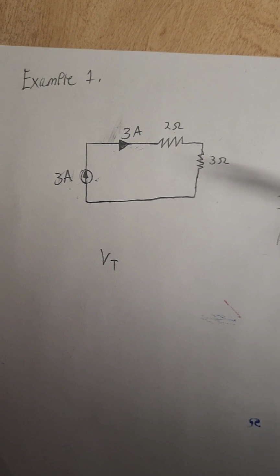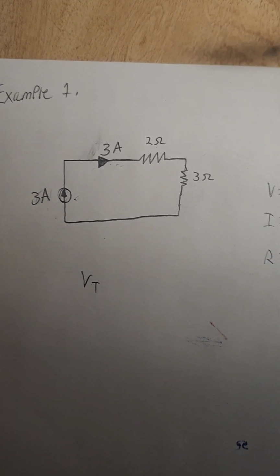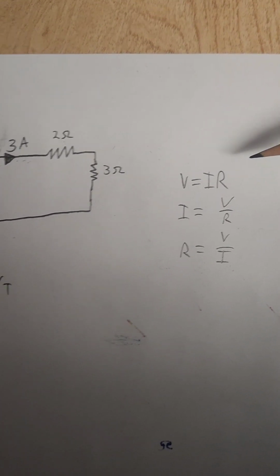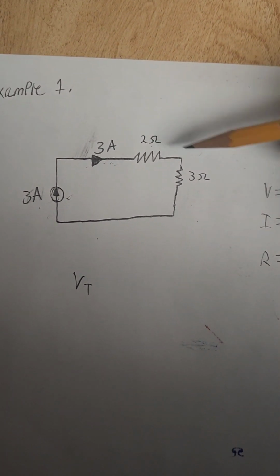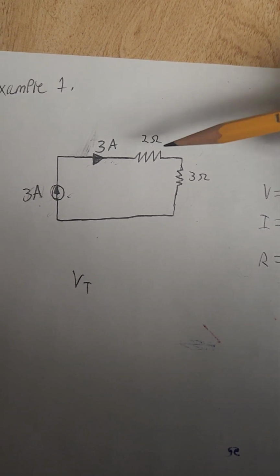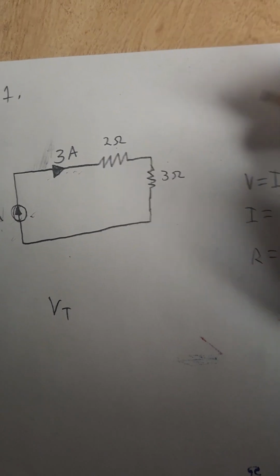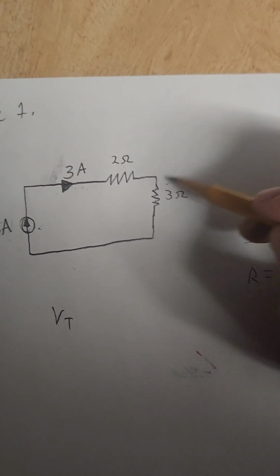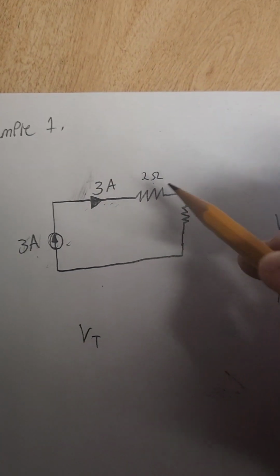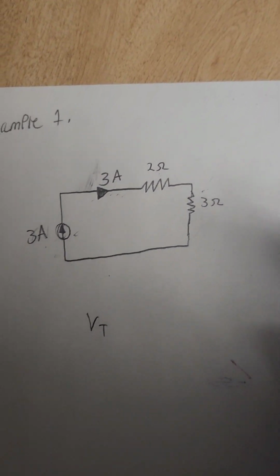The way we can find the voltage from the source by having the current is by using Ohm's law. So voltage is equal to I times R. Well, we have 2 resistances in series, so we can just use this equation. We can first do a simplification, though. We can combine these two because they're in series and just say this is 5 ohms, because resistors in series add together. Parallel, it's a little more complicated.